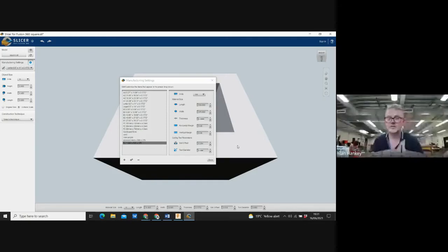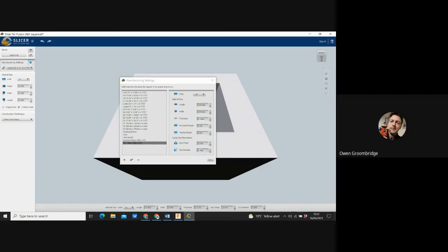Yeah, I mean, this one, for instance, I wanted to do very quickly before we started today. Anybody who was on the slicer introduction, the very quick introduction I did, would probably see me working on this sharp thing. I had to hit it really quite hard to get these things to go in together. So in actual fact, I think we're going to leave the offset at 0.2, but I think we'll put a tool diameter in this as well, because that was too hard to put together. So let's put 0.2 on the thickness of our laser. It's probably 0.25, but I think it's 0.1.